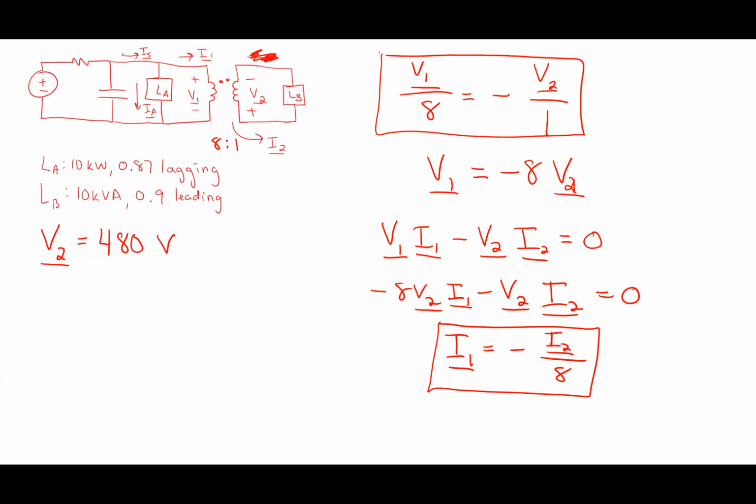Yes. So, are we always going to solve for V1 and I1, just on one side of the equation, or can we do V1 and then solve for I2? That doesn't really matter. Yeah, I mean, it doesn't matter. Somehow you got to do the voltages first to get some relationship, because that just comes from knowing the turns ratio. And then in your power equation, you just got to substitute in one way or the other, either for V1 or for V2. Right, the V2s cancel here, and then you're left with some relationship between I1 and I2.